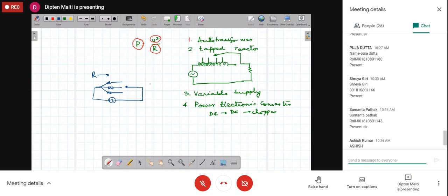If we have a delta or three elements, this is of course a speciality of three resistances. If we have three such resistances and this is a three-phase supply, we can connect the resistances in star and delta. Depending upon the connection, in star, the resistance values would become higher, so the power generated for the same voltage would be lower. And in delta, the power generated by the same resistances would be higher because they are connected across the voltage source directly.